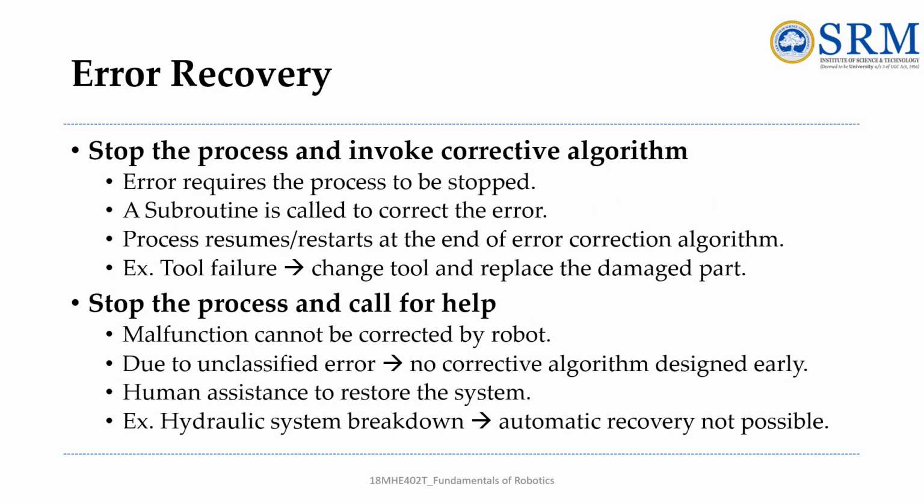Next, the third recovery strategy is stop the process and invoke a corrective algorithm. For example, in case of a tool failure, we have to change the tool and replace the damaged part. After that, the process resumes. So here, this error requires the process to be stopped. A subroutine is called to correct the error.